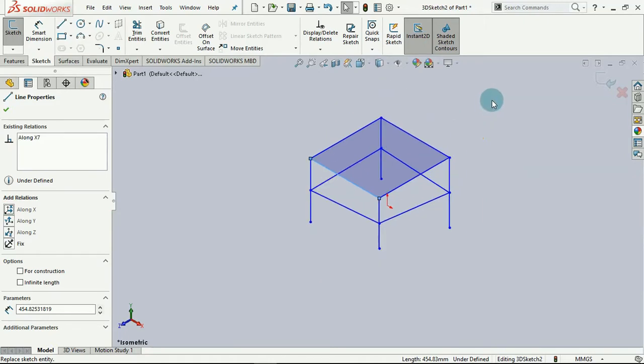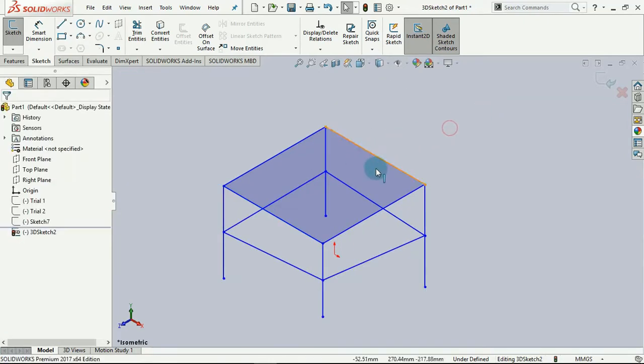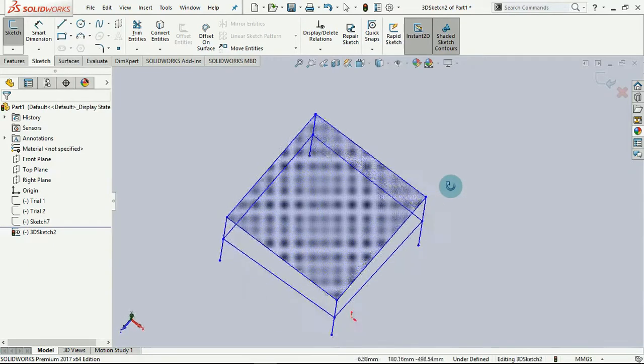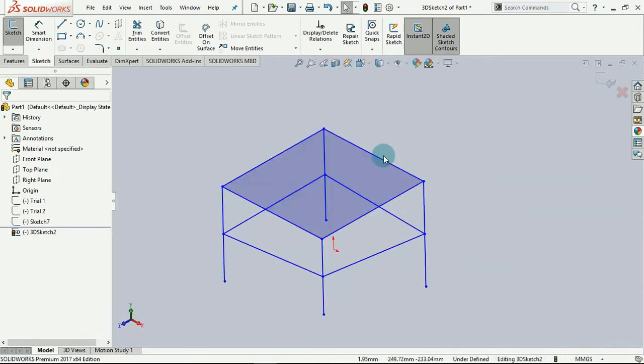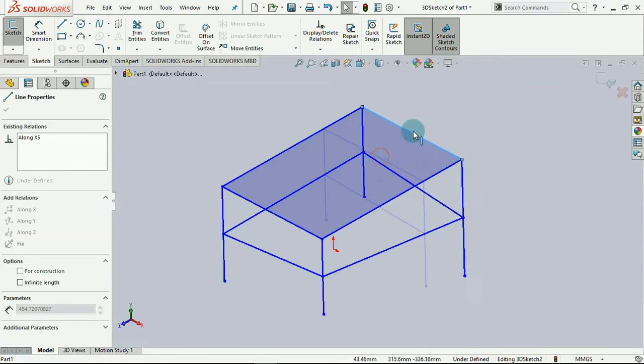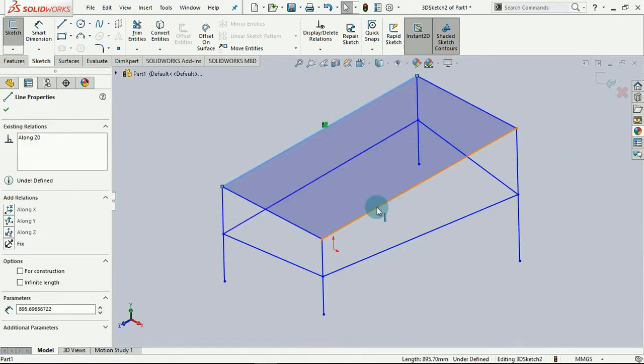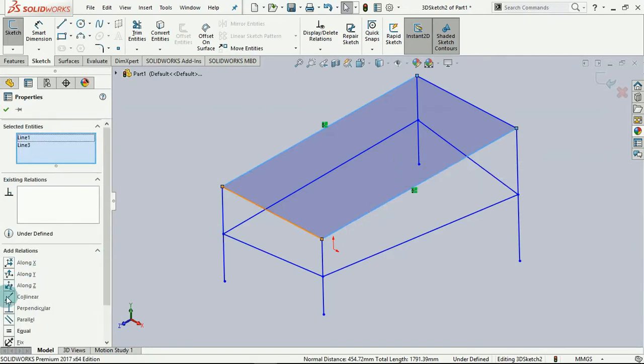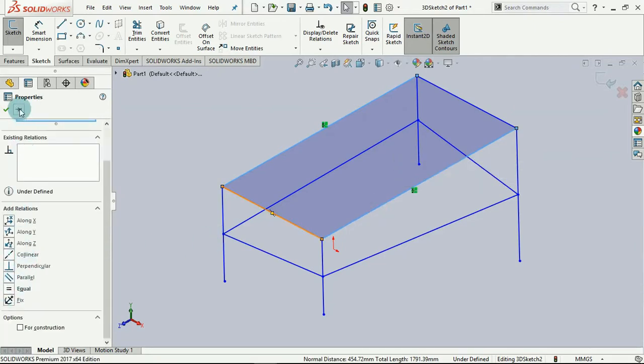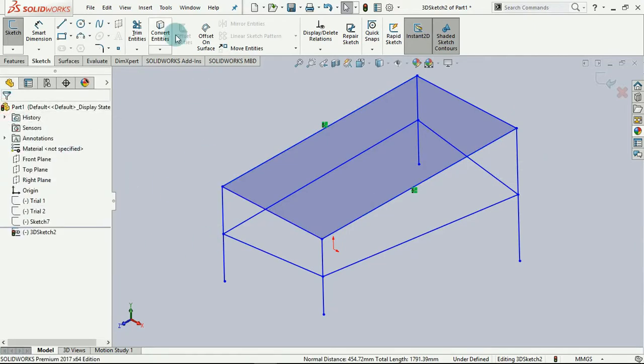Okay, now the thing is, this looks somehow like a square top, but I want a rectangular top. So let's say I drag this, yeah, and that makes better sense. Note you can also use the relations of equal by pressing Ctrl and then coming here to select all of this, just the same way we used with the proper line or with the normal line.